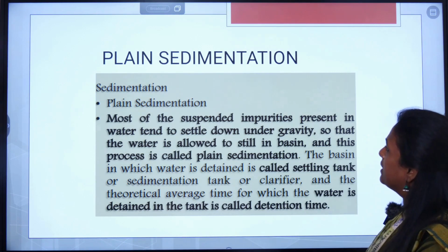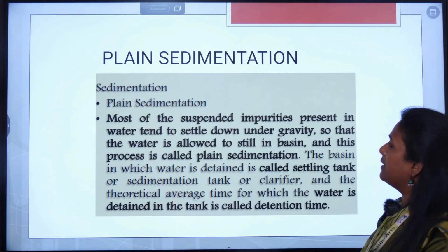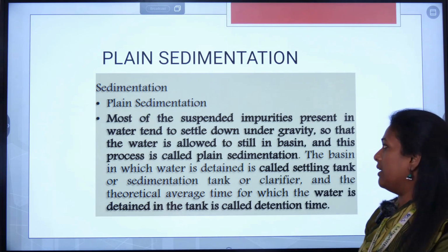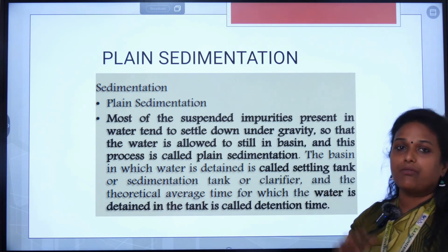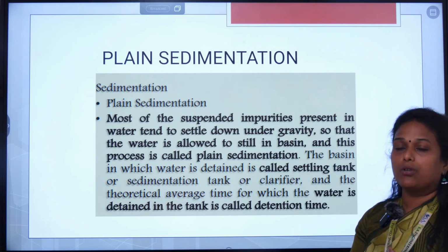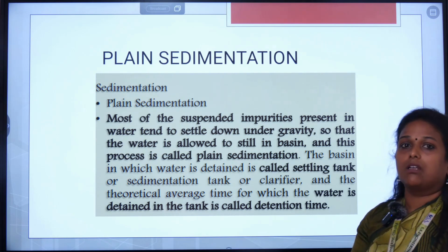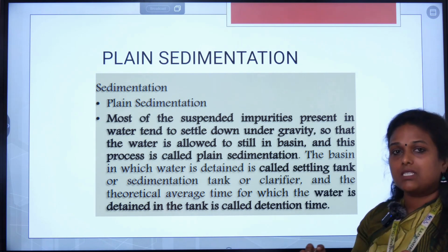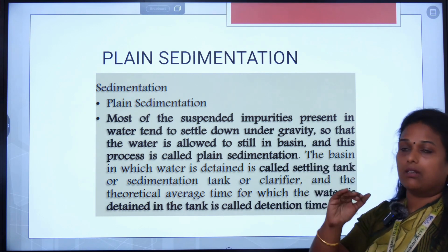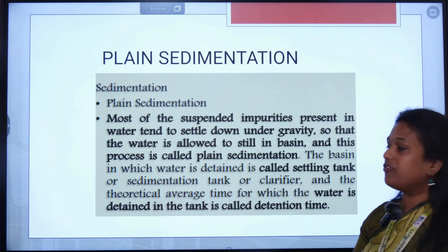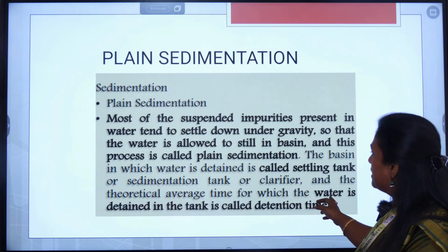So plain sedimentation, as the name indicates, means we are not adding any coagulants. We are making the water stand for a while for a detention period of about 2 to 4 hours, where by gravity the particles settle down automatically, the sludge is formed at the bottom, and the clearer water is taken to the next set of operations. So that is about plain sedimentation.